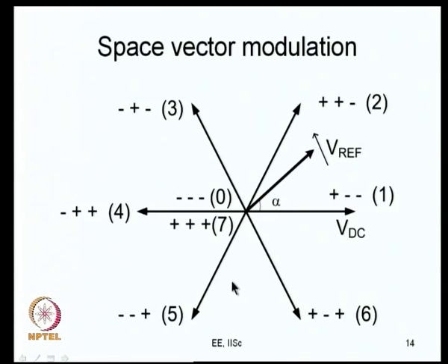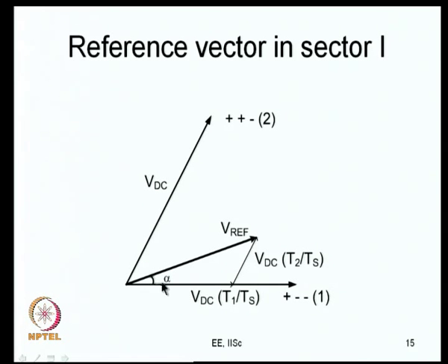And so, now with that model, let us say the PWM inverter is being switched using space vector modulation. As we have been seeing in the last several lectures, space vector modulation basically means a voltage vector is provided instead of 3 phase voltage references, and the voltage vector has a certain magnitude Vref, which is proportional to the desired fundamental voltage. It is revolving at a constant frequency, the desired modulation frequency, and this is sampled once in every subcycle Ts, and within that you do a time averaging.